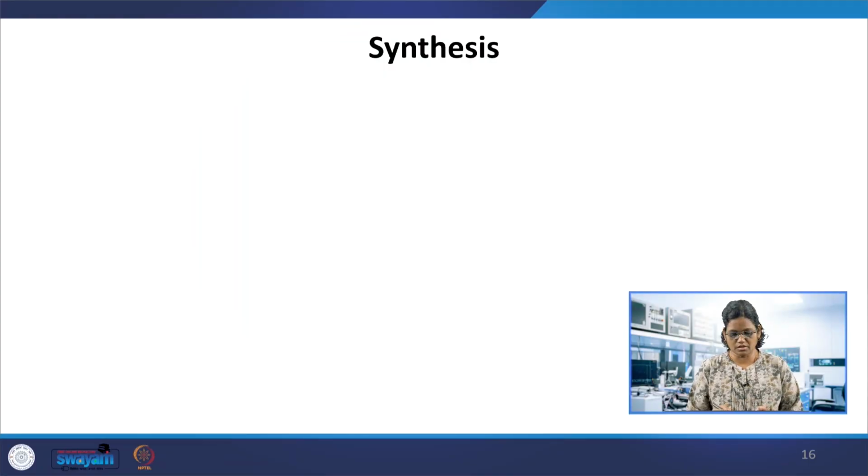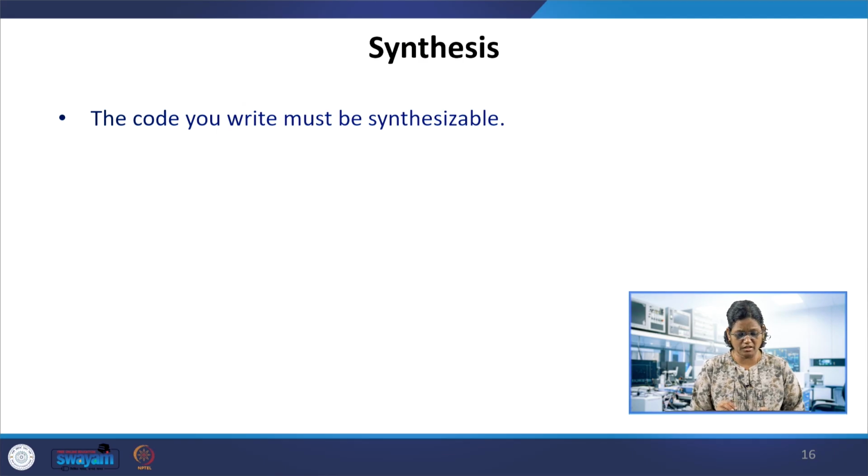Now the synthesis process. We had the test bench, then the simulation, and then the synthesis, very briefly. The code you write should be synthesizable. The synthesizer should find a suitable hardware element, logic gates, or resources of the hardware FPGA for your code. If it cannot, then we have to rewrite the code.